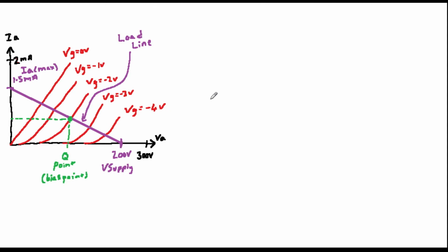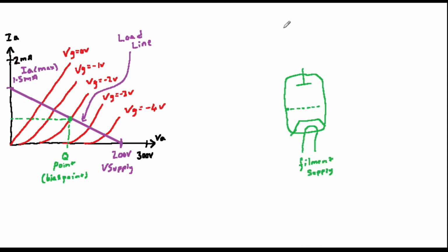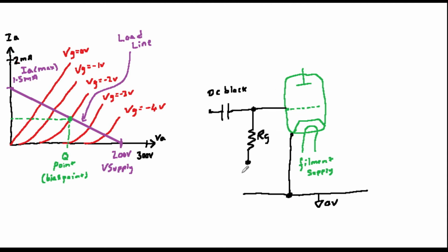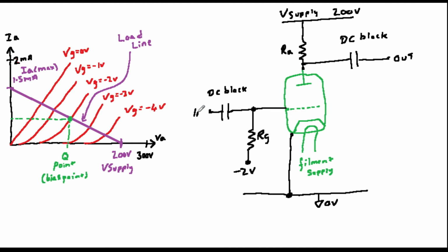Sketch the load line on the characteristic graph of your triode as shown on the screen. Place a line nicely in the middle of the graph and away from any potential maxima, like the maximum allowed voltage or maximum allowed power dissipation. The amplifier that we're going to produce will look like that shown on the screen.